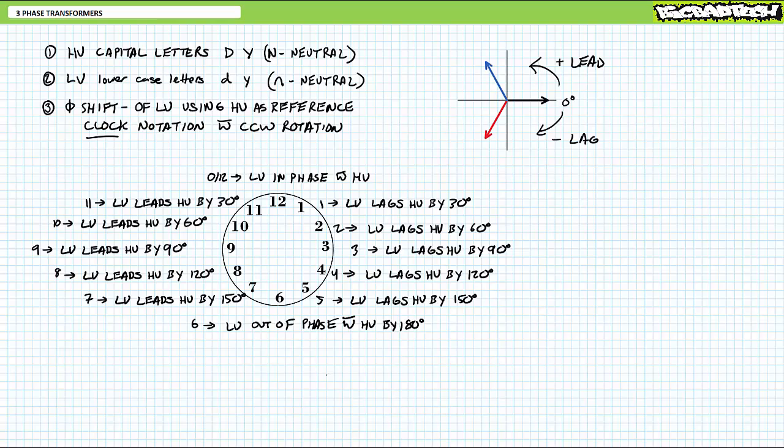Clock and displacement diagrams still stick with a counterclockwise direction of rotation and the same definitions for leading and lagging, but rather than starting out the 0-degree circle out on the right-hand side, they locate 0 degrees up the top. It isn't too big of a deal since all you're doing is effectively rotating a regular phasor diagram 90 degrees counterclockwise, but it's still annoying for those that vainly seek consistency and sense in our upside-down world.